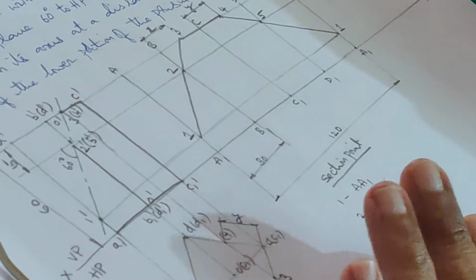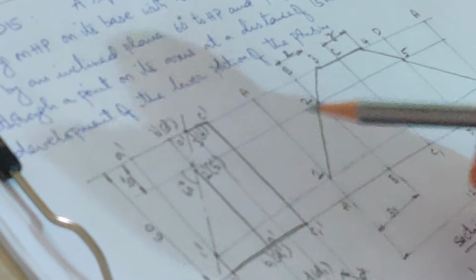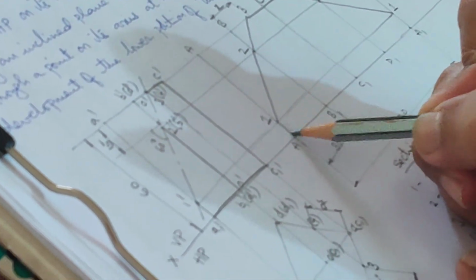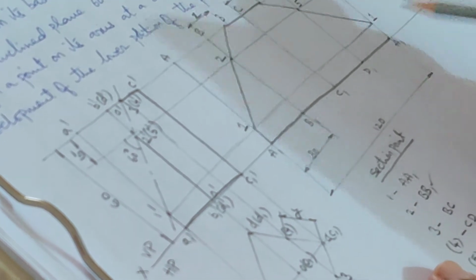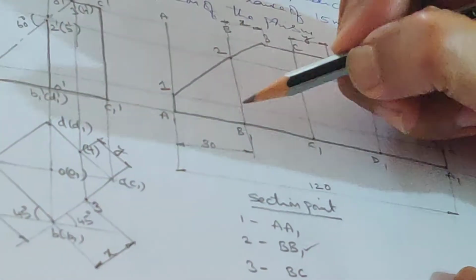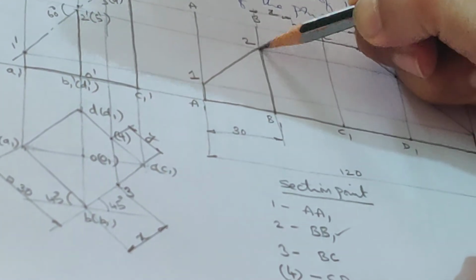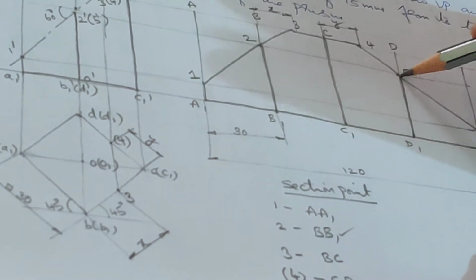Now you are asked to draw the development for this portion, the entire portion. So you have to include this as well. Whatever is required you have to show as dark. And wherever the sheet has to be folded, you need to fold it along the longer edges. So even those lines will be made dark.